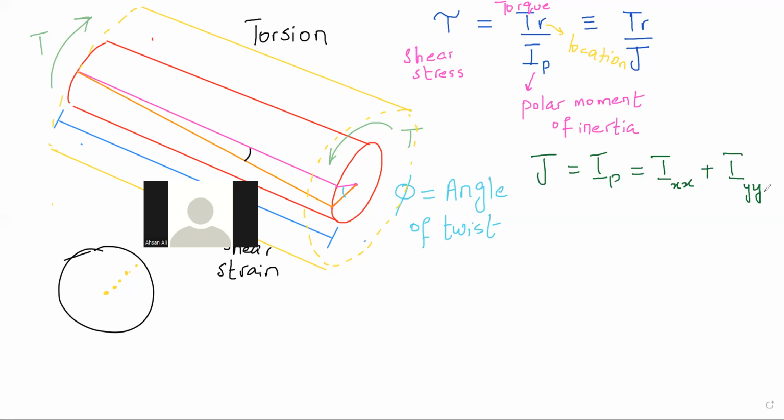should I explain? This object is rotating about one particular axis, right? And it has definitely a moment of inertia, resistance to motion about one particular axis. You change that, then this is another axis. So this is the deal, that polar moment of inertia means that if I add both of them, then for the object, it gives me polar moment of inertia. And in a twisting problem, you need polar moment of inertia, not the individual one.